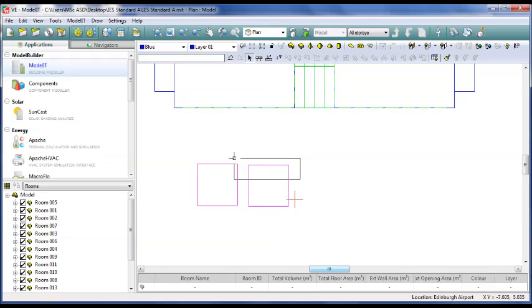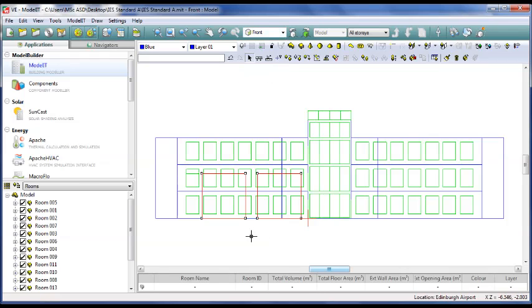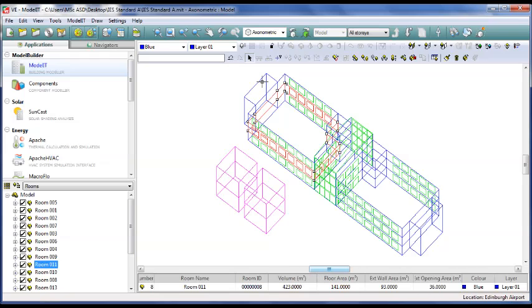If I highlight both of those, this would be the normal way that you would add an extra floor. So quick look at the axonometric, I've already got those two highlighted. And now if I go to the front plane, I use the same button again, grab the corner, click and drag, and suddenly if we go to axonometric, we have two tall buildings.